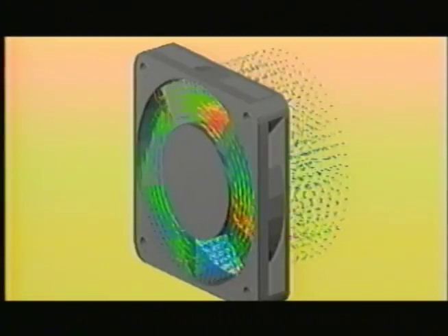Let's view the animation of the airflow over time. The flow pattern changes dramatically when a blade passes over one of the two narrow ribs. The first narrow rib stirs up turbulence, which is made worse by the second rib. The wide rib tends to smooth and straighten the airflow. Turbulence generated by the narrow ribs blocks airflow in 1/3 of the fan.